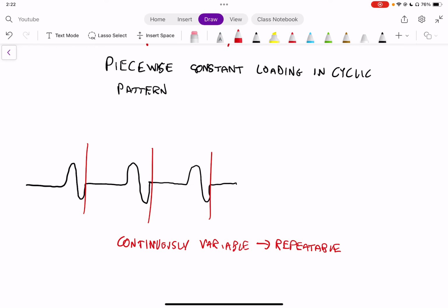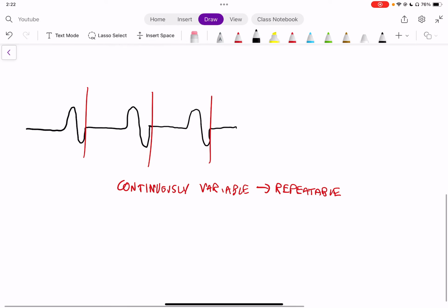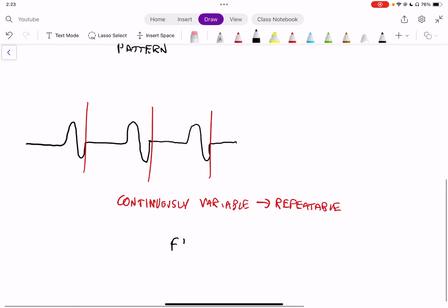The first thing we can write about the analysis of our system is to recall from previous videos the equation that says F L to the power of 1 over a is equal to a constant. That gives us a value of how much force and life we can have. The more life we have, the less force we need, or the more force we have, the more the life of the bearing is reduced overall.